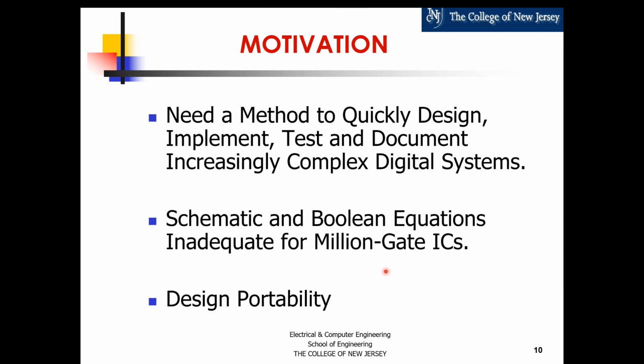There is a language called EDIF, the Electronic Design Interchange Format. It doesn't work very well because schematics are graphics, and there's so much detail and redundancy. So it's great that Verilog is a standard. You can take your same Verilog and target a Xilinx FPGA, or you could target an Intel FPGA, without having to redo your design. That design portability is a big advantage of using a standard hardware description language.